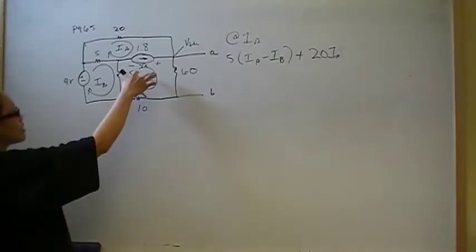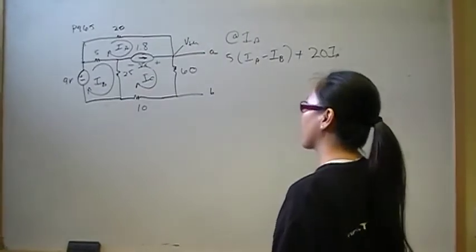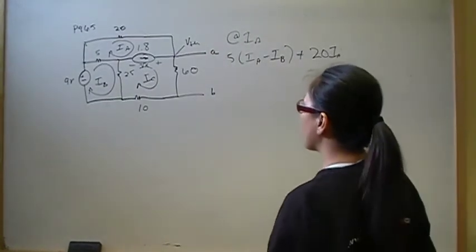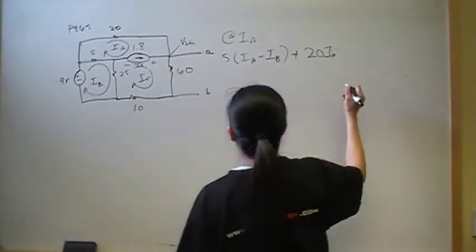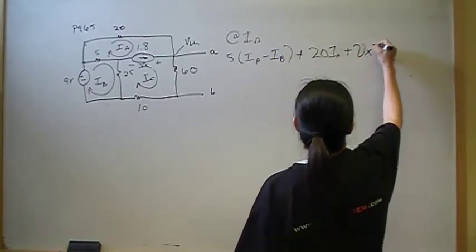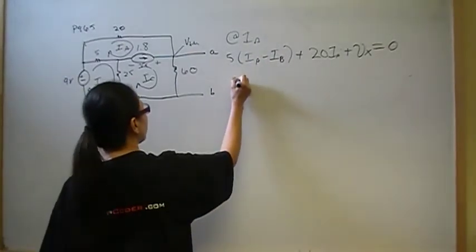What you would do is just give this a voltage, and remember that the mesh method utilizes the KVL, Kirchhoff's voltage law. So then this voltage drop here is some unknown Vx, so we're going to go plus Vx. So we have 3 drops, and all that sum is equal to 0. So mesh at IB then.